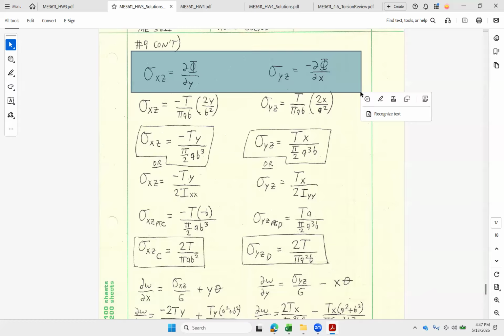If I put in a negative x, on my left-hand side, the stresses are going down generally. So that works out. And then the xz, if I'm on the bottom and I get a negative y, that converts to a positive xz stress. And if I'm on the top of the ellipse, it's got a positive y, so this comes out pushing negative, or to the left. Max values are going to be at those quadrant points, and I can see them right here.